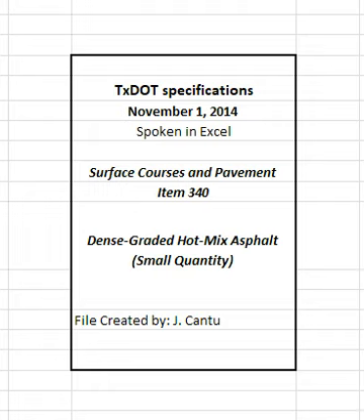Coarse aggregate from RAP and recycled asphalt shingles, RAS, will be considered as Class B aggregate for blending purposes. The engineer may perform tests at any time during production, when the contractor blends Class A and B aggregates to meet a Class A requirement, to ensure that at least 50% by weight, or volume if required, of the material retained on the number 4 sieve comes from the Class A aggregate source.